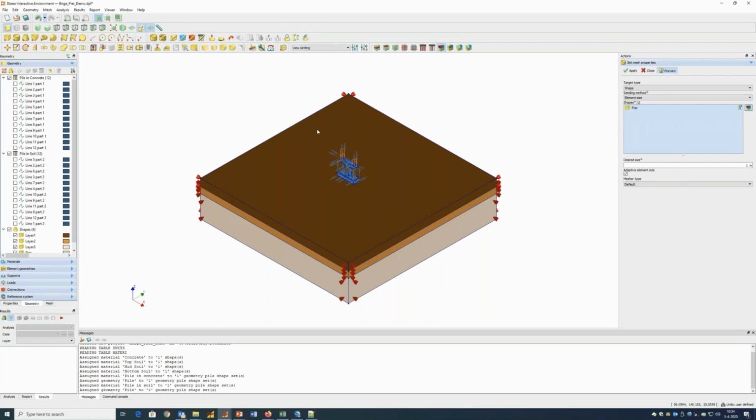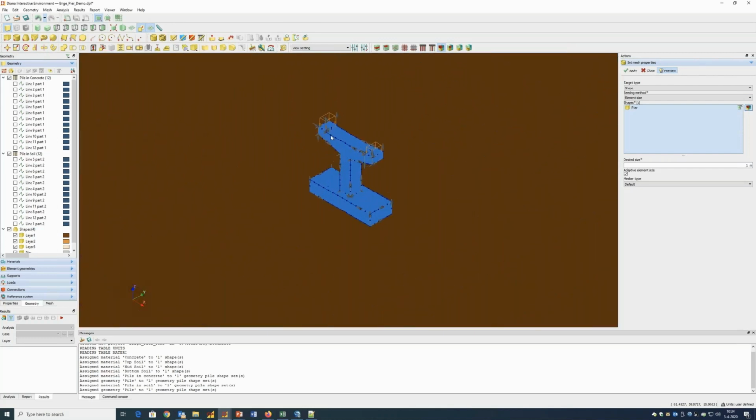If I click on preview, you can see the mesh sizing, and you can see also some arrows. These arrows are basically giving you the orientation of every edge. This is quite convenient when you need to specify a grading, and you need to know the start and ending point of the edge. So I click apply.